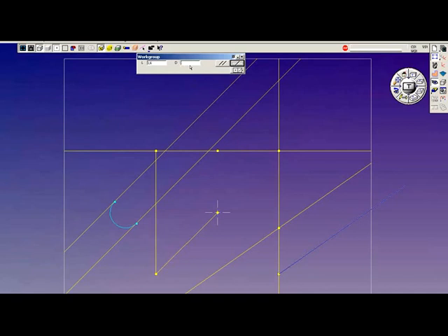I'm going to type in a distance of 0.5. Choose the single feature creation tile, and I get two choices. Once again, select the desired feature or features. I'm going to select this one here, say OK, and this line appears or stays on screen.